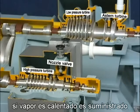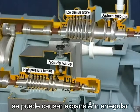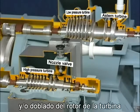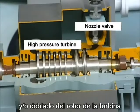If warming up steam is supplied without the main engine turning, it may cause irregular expansion in the turbine's structural elements and/or bending of the turbine rotor.